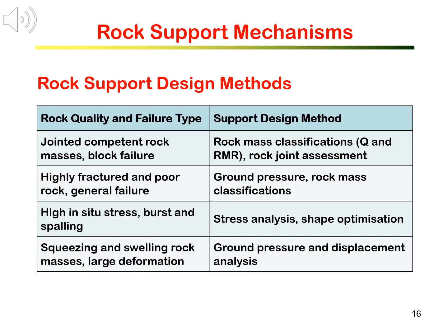Rock support for underground excavation can be designed by a variety of methods, ranging from empirical to analytical and numerical. Rock mass classification systems are well-established methods for rock support design. The two widely used systems are Q and RMR. We will learn in detail how to use Q and RMR to design rock support for tunnels and caverns later. Assessing joint orientation and using projection methods to determine the potential of block and wedge fall and sliding can help to design spot bolting.